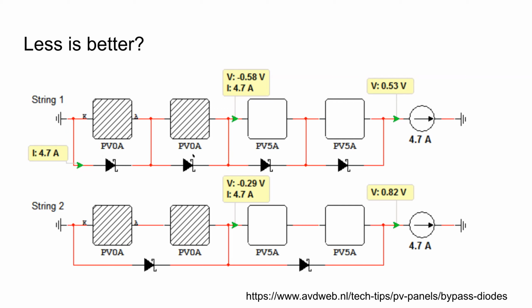And some teams are like, hey, why not just give every solar cell a diode? That might not be optimal either, because the more diodes you have in series, the more losses the diodes create. So ideally you would just bypass all the shaded cells with a single diode, but then you never really know where the shadow is. So in this example, you would rather have the bottom scenario because your bypass current only has to go through one diode, which is 1 times diode loss.